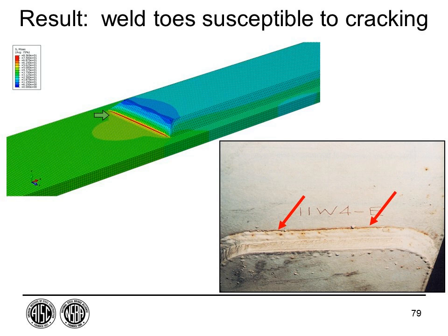Yeah, there's nothing wrong with doing that. When you do that, of course, then there's no variability, right? You'd have to be careful when you do that, because the fatigue curves that we use include the effects of defects from welding, residual stresses, all those things. With Paris law, if you ran the number 10 times, you get the same answer. If I do 10 fatigue tests, I get 10 different answers, right? So somewhere you'd want to put a factor of safety in that, I guess is what I'm getting at.